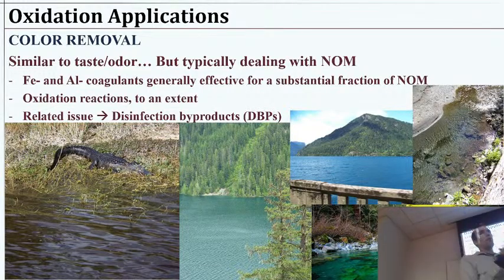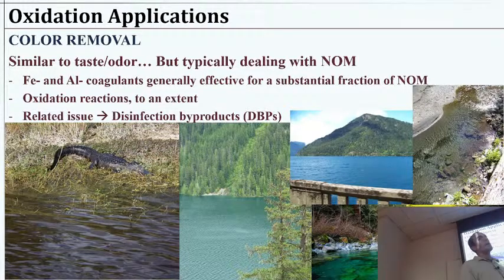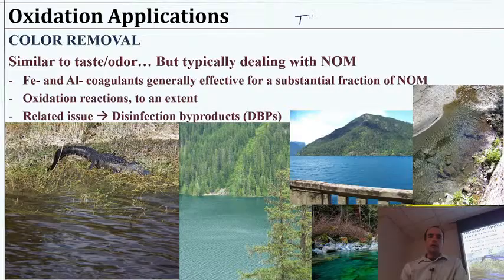If you're using an oxidation process to try to remove just generic organic matter, and there's a lot of organic matter, you do come into some potential problem of disinfection byproducts, especially if you're using some halogens or if there's some halogens in your water to begin with. Introducing a highly oxidizing environment could cause the halogenation of molecules. So we often talk about haloacetic acids or trihalomethanes, THMs.